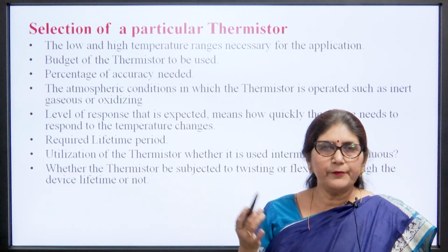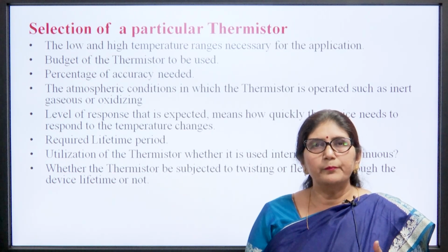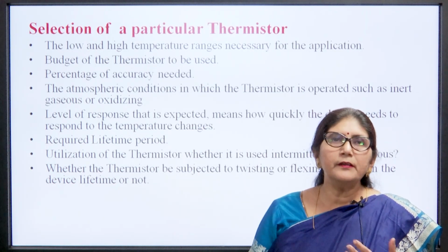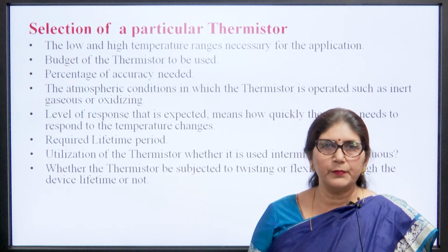Suppose in a system the temperature is varying very fast, then we need a thermistor that will respond to that fast change in temperature.